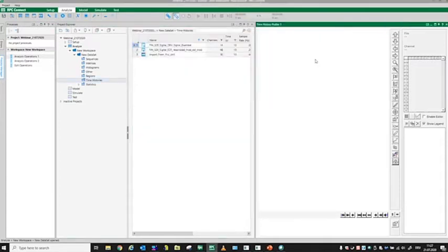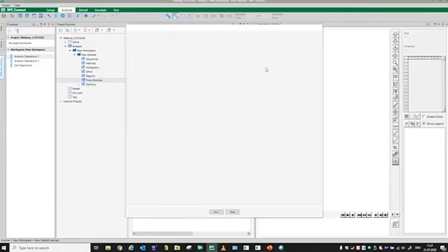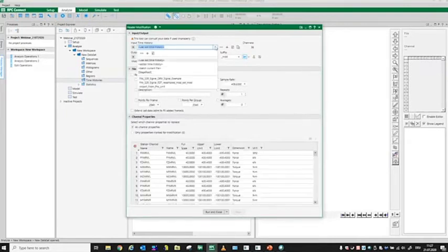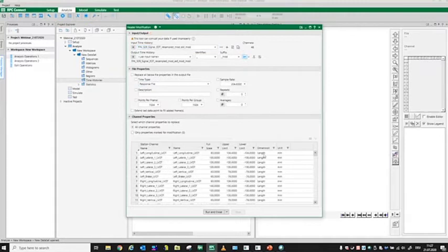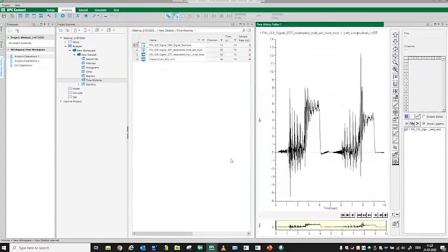So for example, if you go into a header modification, and let's grab our time history, which we used for an example here. Let's grab this time history and say, I don't want to have the left longitudinal in millimeters. I want to have it in kilometers. I just select the unit, say run and close. So I will get a file, of course, called mod again, as you know from RPC Pro.